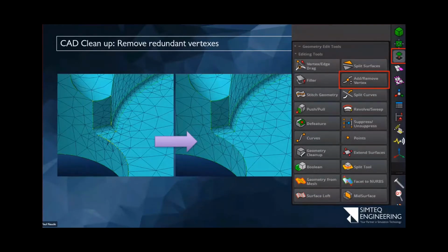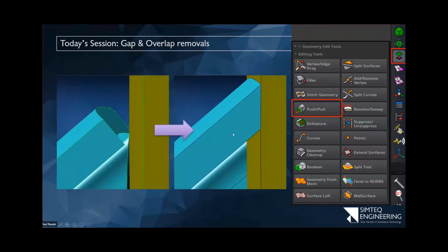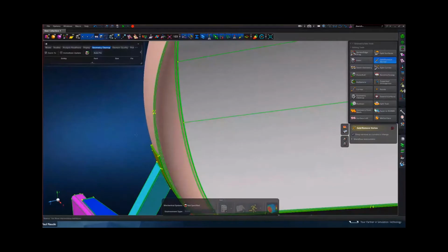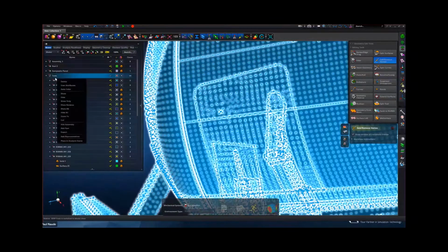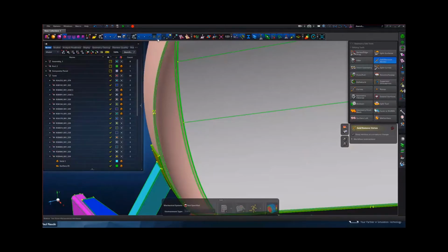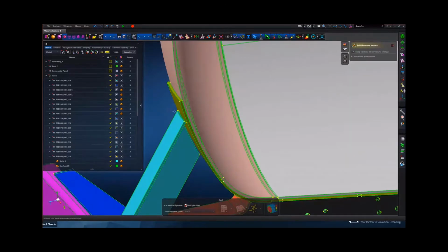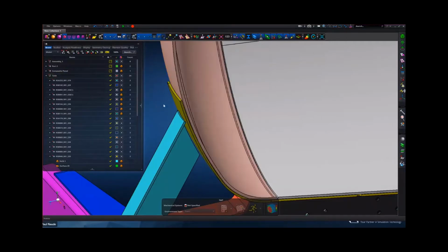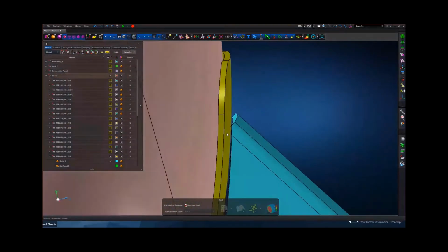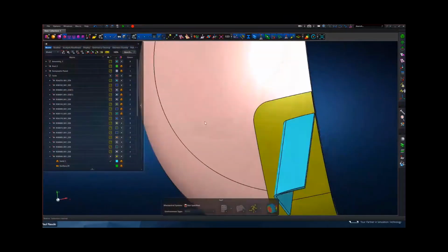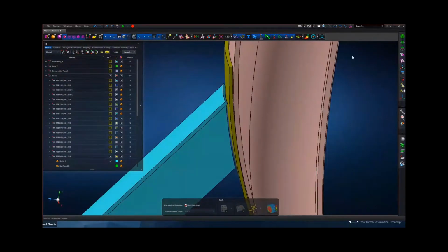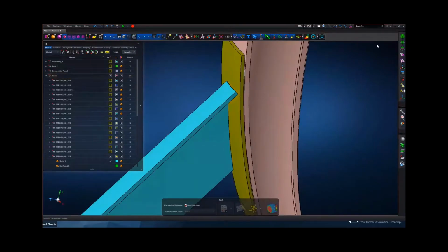Right, so now we skip over to the push-pull tool. And this one is of immense value when working with solid models. We've seen in this original model, let me just show the tank only and hide the meshes as well. Okay, so if I maybe just show these ones only, we see that these solids were not properly modeled from the CAD side, and if this was a model that we wanted to solid mesh, it would obviously not work because they don't have anything in common to connect with one another. So a nice tool to use is the edge drag tool.